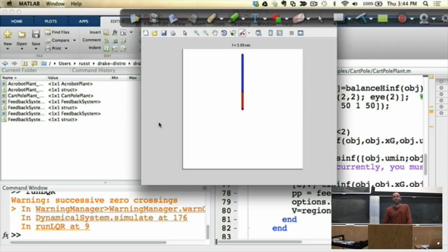We're going to give you a very good answer to that, but it's going to take a little work, because you have to use convex optimization and bring some tools down. But actually, that's a perfect point. If we are going to tile the space with controllers that are good, one of the things that we need to know is when that linear controller stops being useful for the nonlinear system. And it turns out that's a problem we can solve nicely with some good tools. We'll be able to find regions where I can guarantee the linear system is going to work.